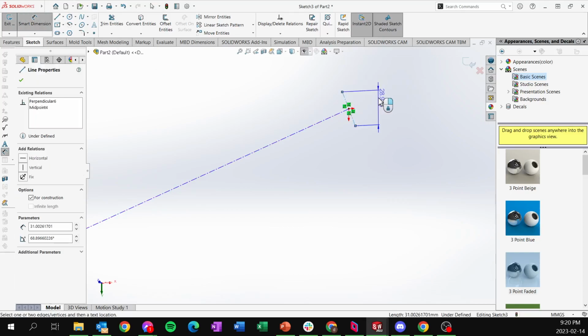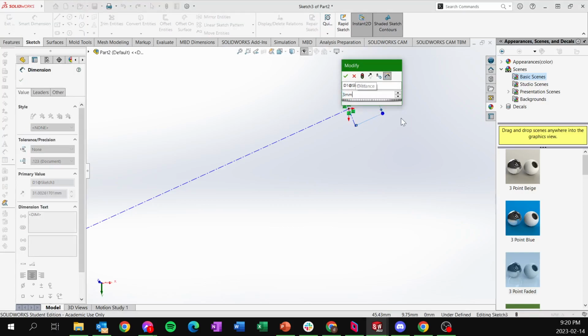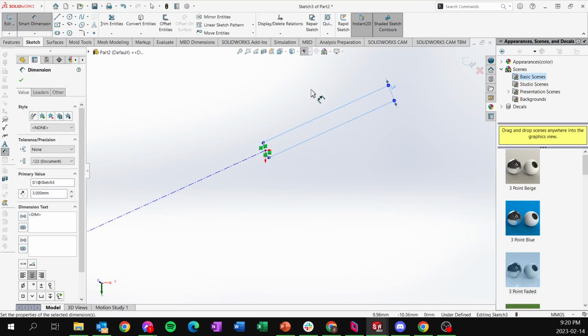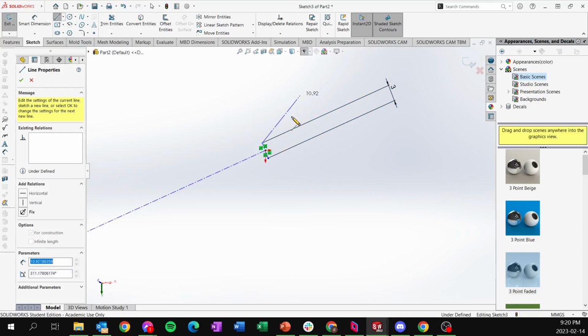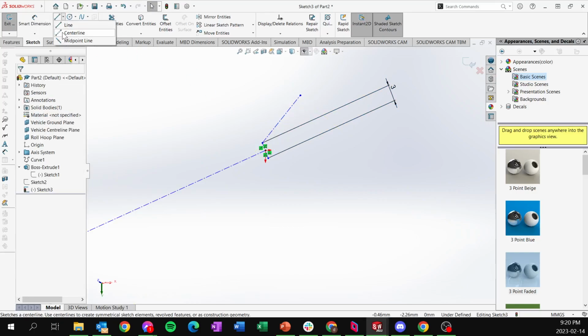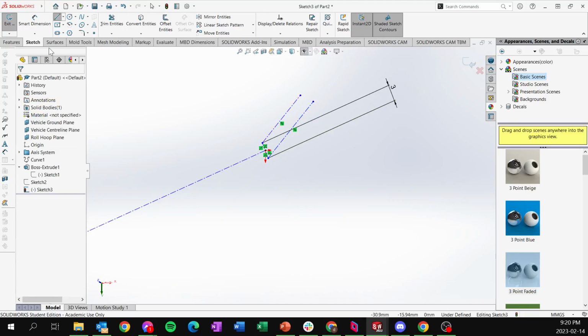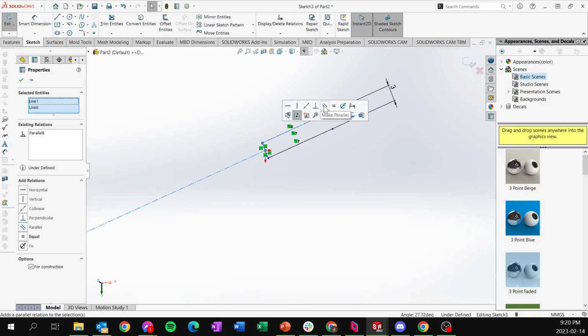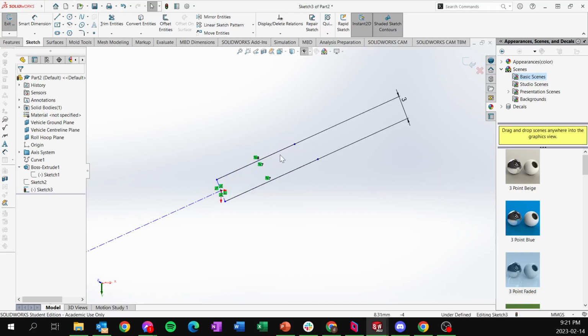So we're going to make this maybe 3 mm. And then what you're going to want to do after that is define these two lines, and these are going to be your trailing edge tangencies. Those are going to be parallel. For sake of simplicity, we're going to make these parallel, but theoretically you don't have to make them parallel. You might actually want to not have these two be parallel. You might want to have them at a certain inset angle.